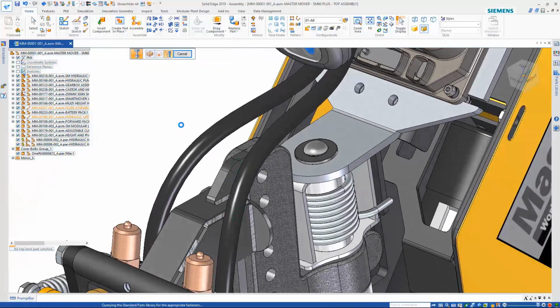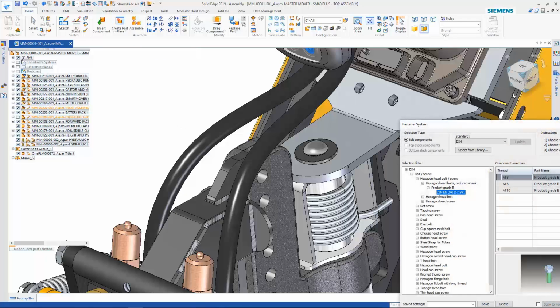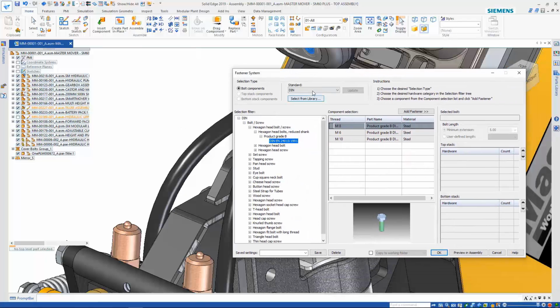So we know the clamp depth we're going to have on these parts. This is then going to look into the fastener system database. So let's just give that a while to load. Okay, there we go. So we've got the correct standard. We want a DIN standard on there. We did 10.9, so I want to be at 10. We can decide any kind of different bolts. I want to do a button head socket screw on there, 7380 M10. Now click add fastener.